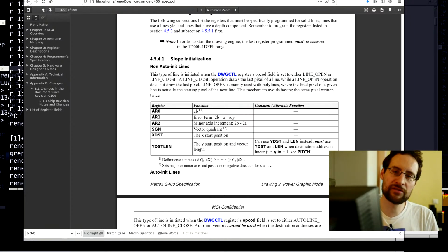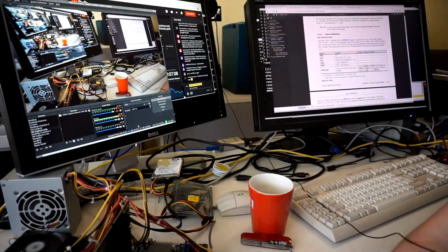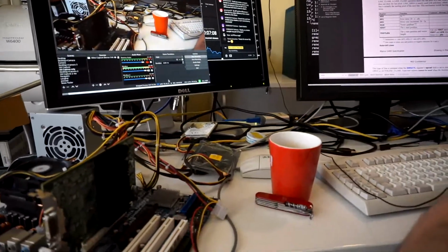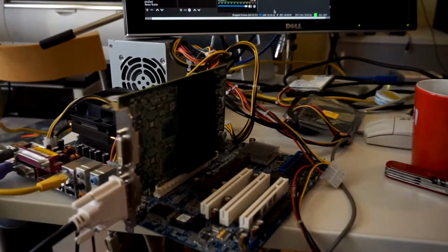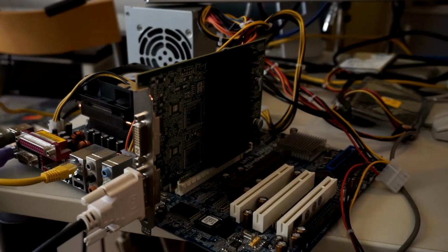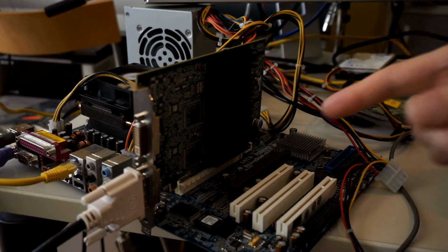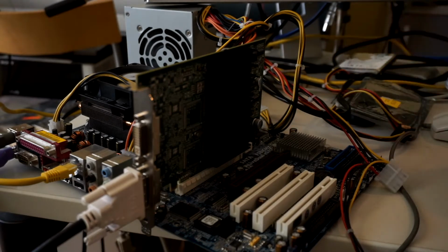Steer asks in the comments in the audience, is this PCIe? So this is PCIe, but I actually got two, since they existed in all flavors. In the meantime, I purchased this for a YouTube video about a decade ago, so this is a little bit darkish. This is PCIe, as you may or may not see. I also have a PCI version. The PCI version is exactly the same, it just has a PLX PCIe to PCI bridge. Otherwise, the layout and everything is exactly the same, just on the back side.